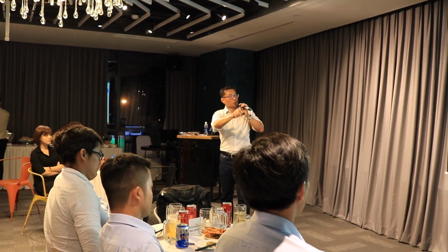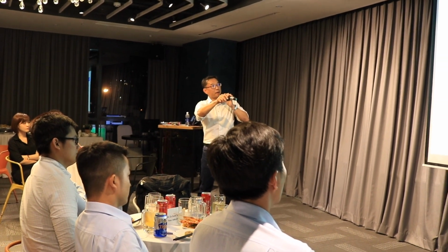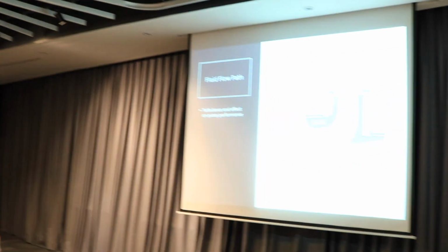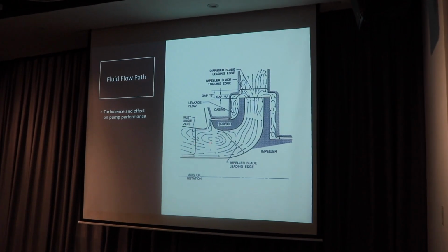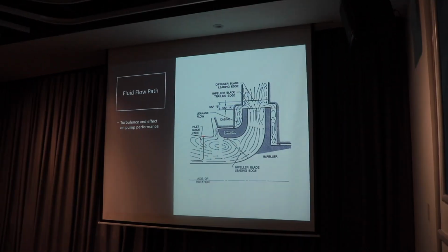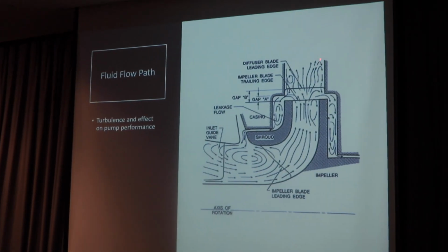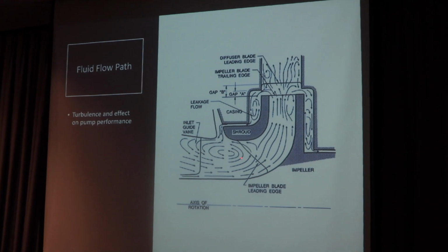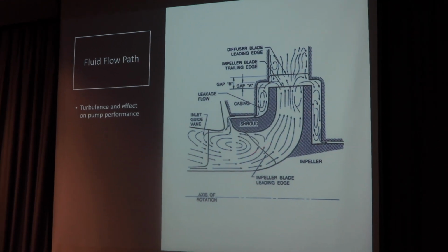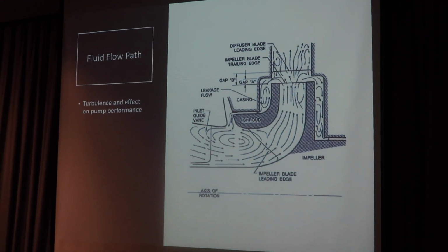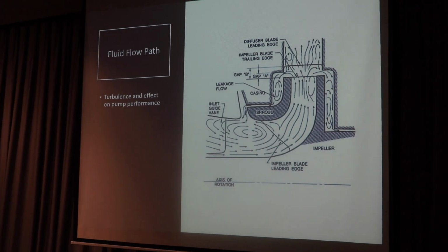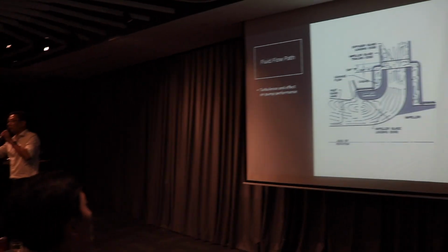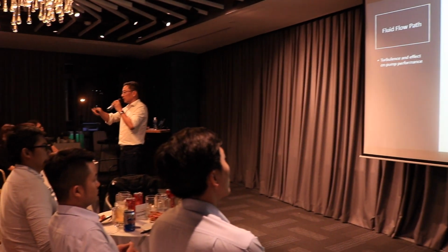Alright? So what you want to do is be at the best efficiency point. Okay? This is a better picture of just now. So you see it creates a turbulence because of this recirculating, it's not going out. So you're stuck here. You look at the amount of fluid that goes in, it's only this part. Very little, half. So suddenly you go and look at the flow meter and say, hey, how come only 50% performance? This is the reason.